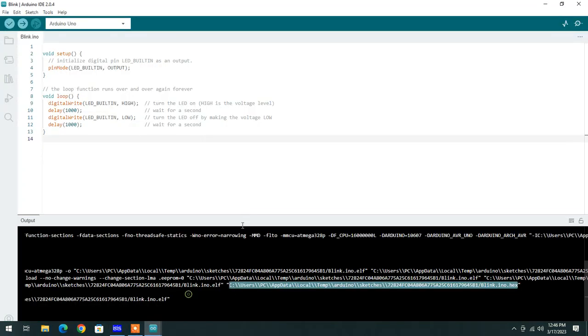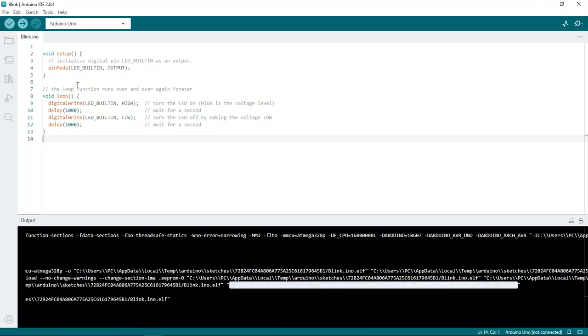This is how you can cross-check the output with the simulation by writing and editing code in the Arduino IDE. Suppose you are looking for a specific pin, then you need to do a declaration. Using the int data type followed by any user-defined name, I'm just taking red LED, which is pin number 2.